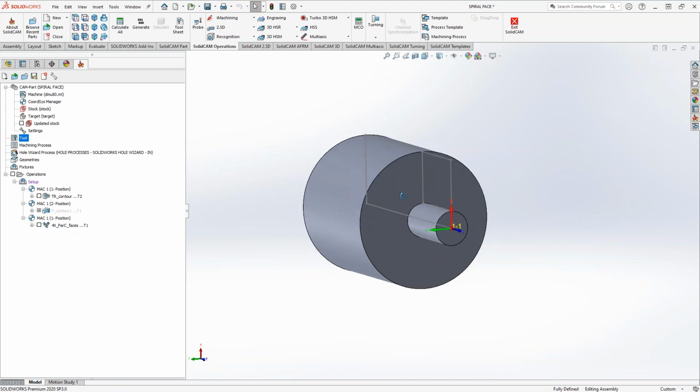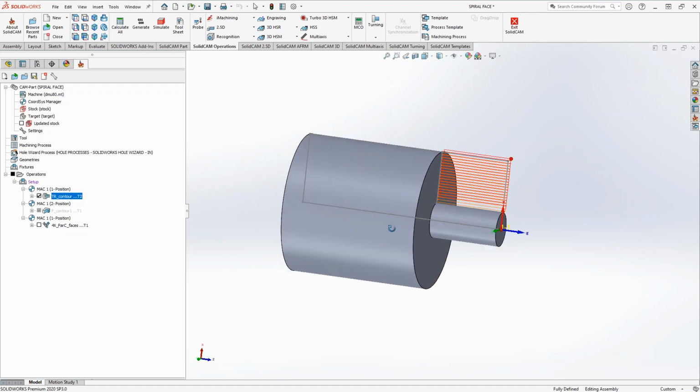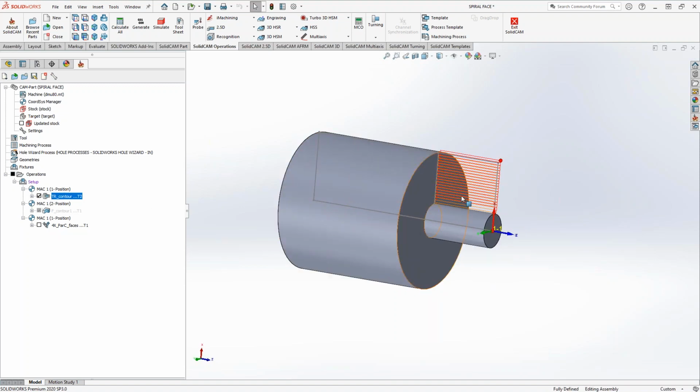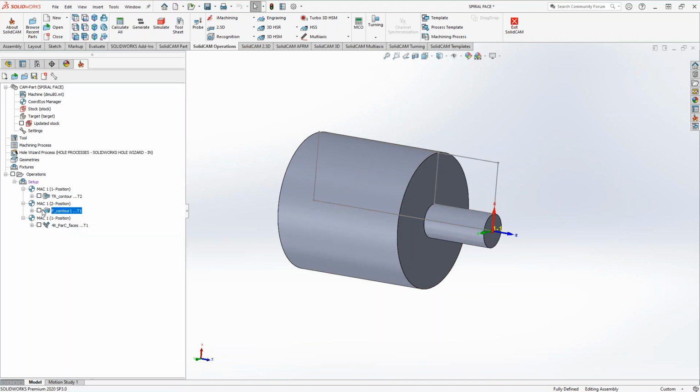Now on this part, in a practical sense, it probably would be easier just to turn it. So I made a really simple part, but you can imagine that if you extrapolate this to something more complex, you'd be able to do a cone, a unique looking shape. You can even do specific features. And this is just the idea that you could wrap your tool path around the center. To show you what I've done so far, I just roughed it out using that turning tool because this is a very basic part. I just wanted to get some material removed here to leave enough so we can see what we can do. And the first thing I tried was a profile toolpath.